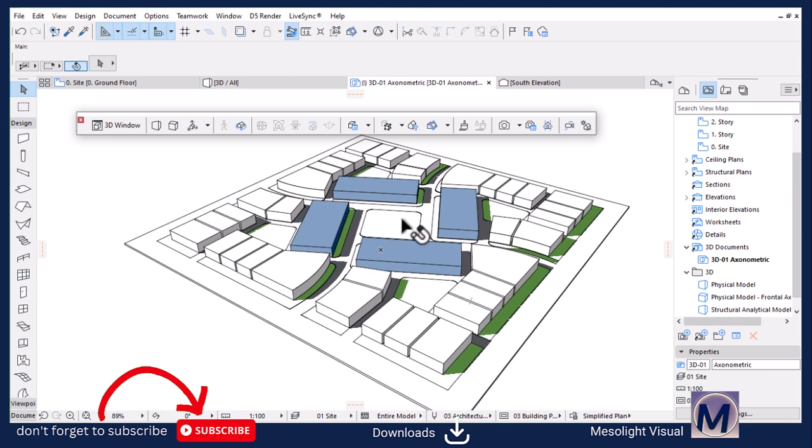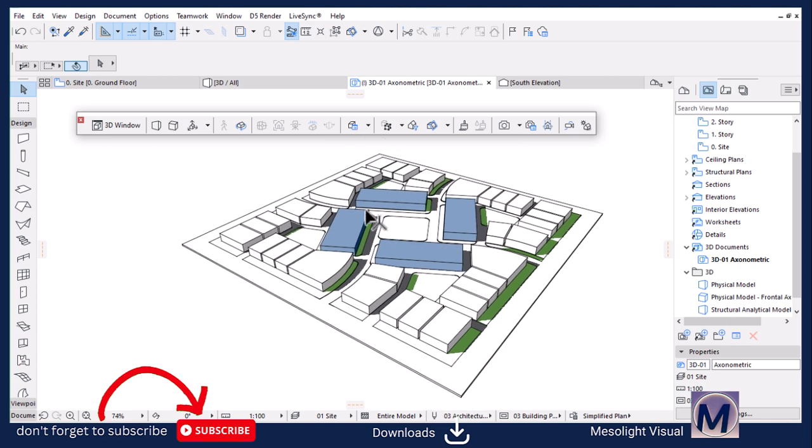So we want to further create depth for these visuals, for this master plan. We want the commercials to pop up because it's the focal point of the whole site here. To achieve that, we need to reduce the intensity of the residential and other elements in the site. But before we go there, let us make sure the green parts are being captured and highlighted. So I'm going to create a graphic override rule that will override that.